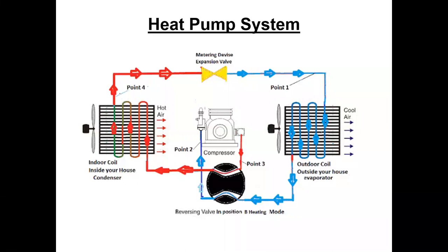It has to boil because you're going to put it in a compressor, and that compressor is not going to like liquid. You'll tear up the compressor if you slug it with any liquid droplets. So this thing is engineered so that coming out of that outdoor coil in heat pump mode, you're all vapor, okay?